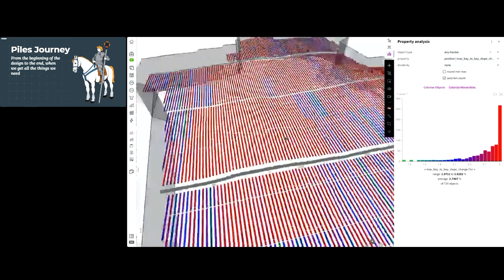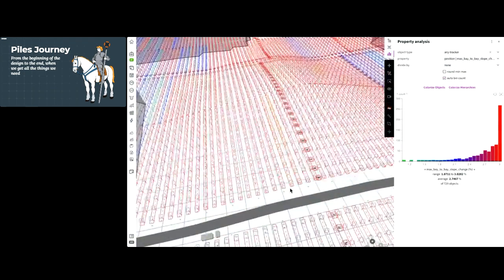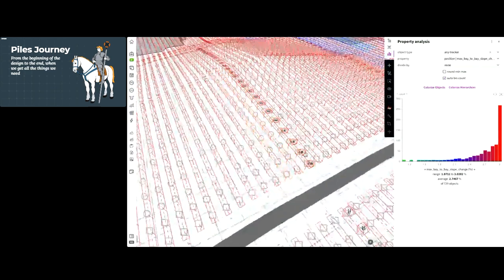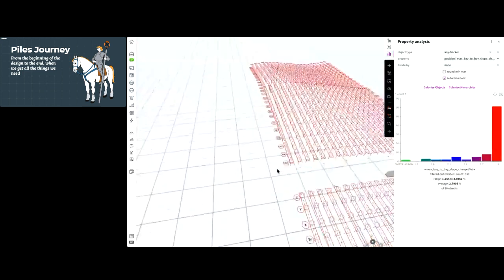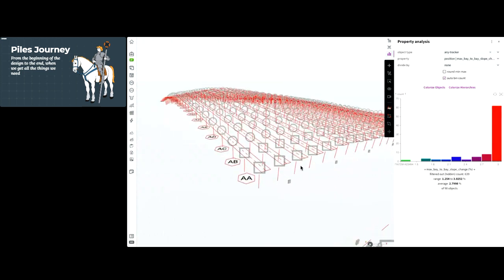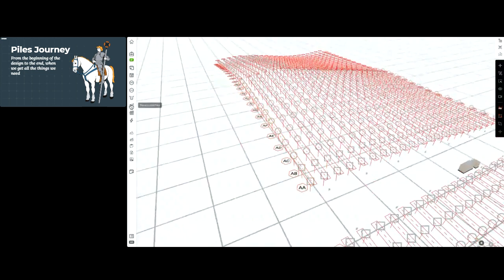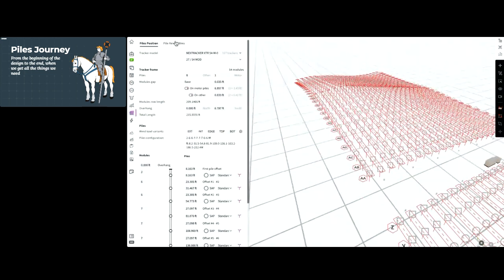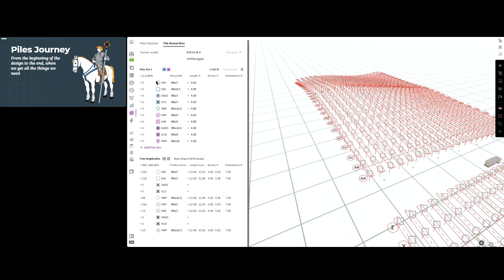And then we're going to start having some fun because we can actually see that we also have the pile markups. So I'll isolate it quickly. We will start seeing that we have pile elevations, top of pile elevations, right? And if I go quickly into pile reveal bins, this is the perfect place where we can start binning those piles.